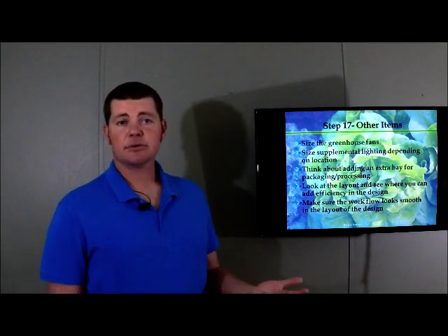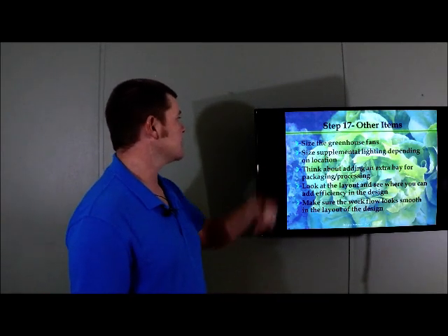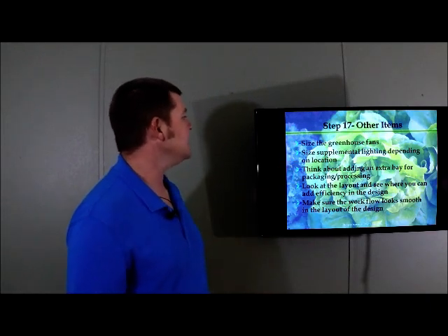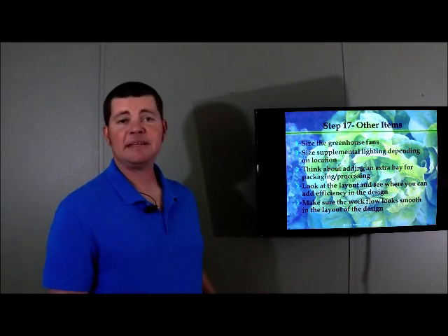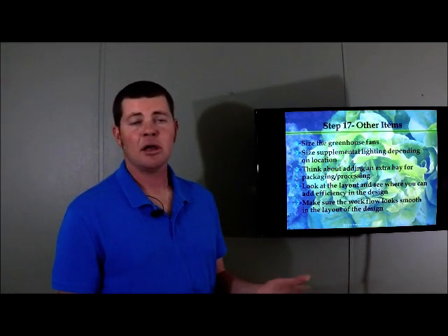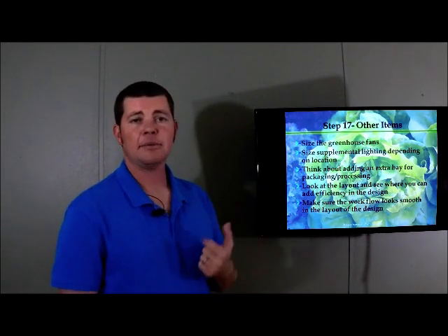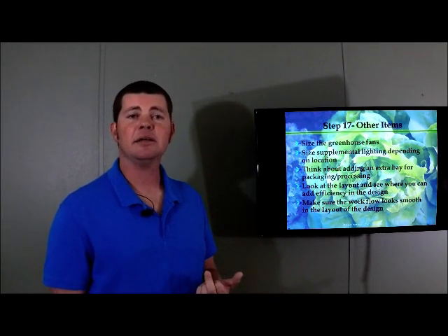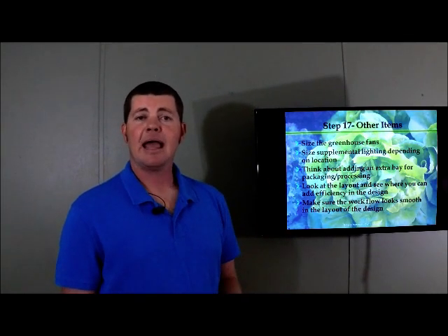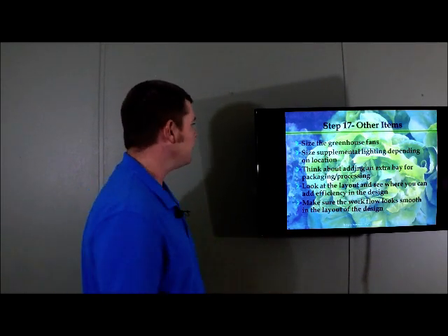So some other items to wrap up in the greenhouse, okay? We need to size the greenhouse fans, which is easy. We need to size supplemental lighting depending on the location. You may be down in South Florida and might not need any supplemental lighting. Arizona might not need much supplemental lighting, okay? But if this was done in a northern climate, you can bet you're going to need supplemental lighting, and that's sized off of the needed PAR per day, and we already know how to do that, okay?